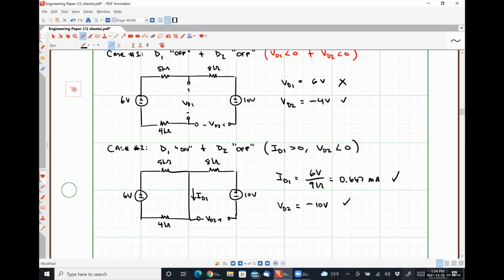No, literally never. It cannot happen that way. It will only be one combination that will satisfy all of your diode voltages for on will be positive, all of your diode currents for on will be positive, and all of your diode voltages for off will be negative. That will only happen for one permutation. So you don't have to say, well, both of these are correct, so which one is really correct? Does not happen. It's always a single individual correct solution.